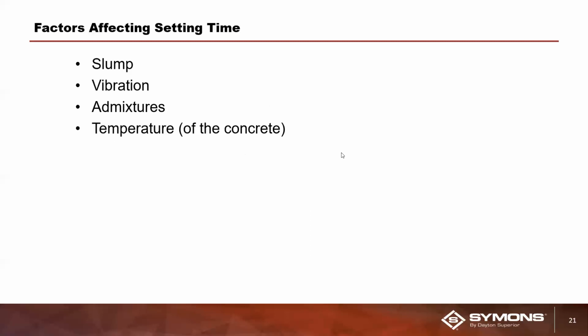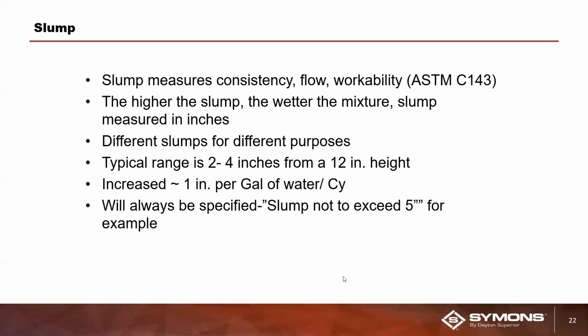Factors that will affect concrete setting time are slump, vibration, admixtures, and temperature. Let's talk first about slump. Slump measures the consistency of the concrete, the flow, the workability, etc. The higher the slump, the wetter the mixture. So slump is measured in inches.